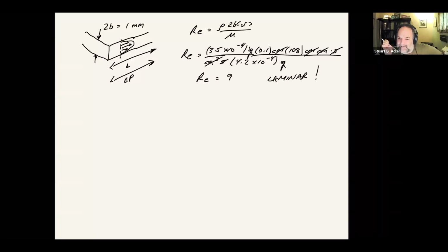So it's not. And this is a general thing in fuel cell engineering. It's both a good thing and a bad thing. The bad thing is that because it's not turbulent, you tend to not get very good mixing. You tend to have a harder time achieving uniformity of the gas flows. You have maximum velocity in the middle of the stream, and then it tapers off to the two boundaries. That can create mass transfer effects at much lower current densities than you would expect. It can lead to maldistribution. There's all kinds of issues with it.